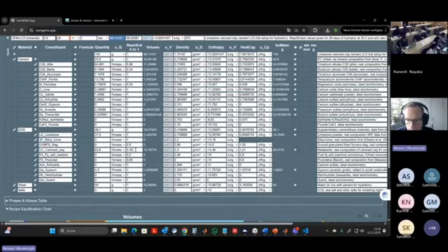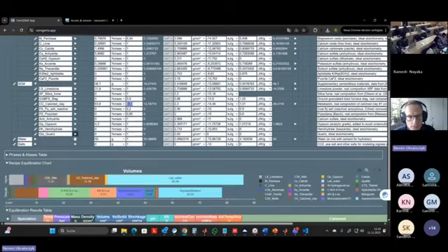For calcined clay, they put only 33% is reactive. So this is this type of mixed clays where there is only 33% of metakaolin, probably. Yeah, that's the typical LC3 composition with mixed clays, raw clays.